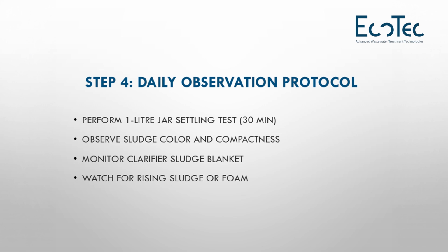Continuous flow biological plants require balance. At partial load, one must reduce reactor volume or supply of air, sludge recycling options, and sludge age. This logic applies to activated sludge, extended aeration, MBBR process. Automation can assist, but it cannot replace biological understanding.